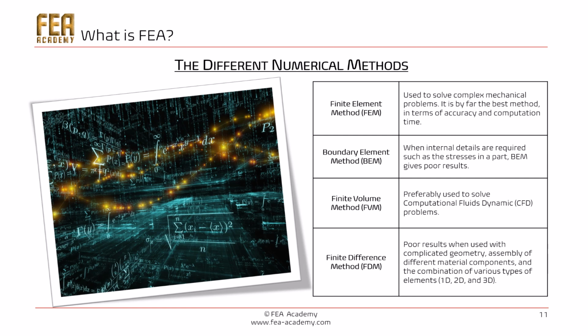When internal details are required, such as the stresses in a part, for example, the boundary element method gives poor results, as it only considers the outer boundaries. In this case, methods like the finite element method, finite volume method, and finite difference method are preferred. The finite volume method can be used to solve stress problems, but it is preferably used to solve CFD problems, the computational fluid dynamics problems.